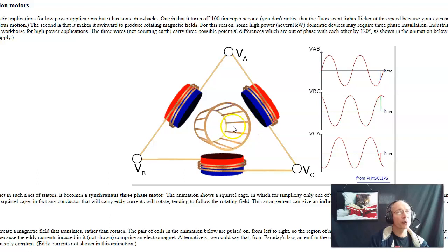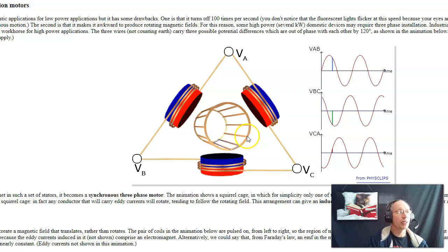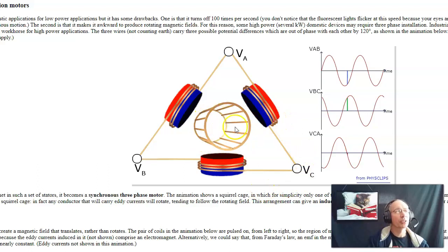Current through a coil produces a magnetic field. That magnetic field will cause torque, fight with the other rotating magnetic field. Synchronous speed is when the two are rotating at the same speed. When this is rotating at the same speed as the rotating field, that synchronous speed, there's no relative changing voltage relative to the rotor, and the current goes to zero. That's kind of how induction motors work. I've got an n-to-1 transformer inducing current in the motor.